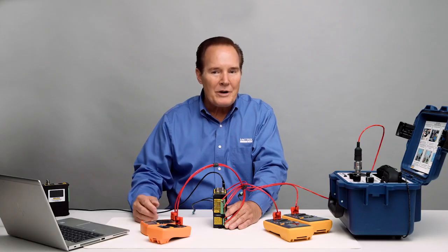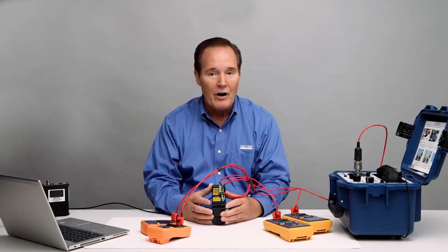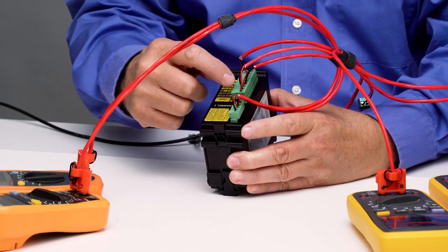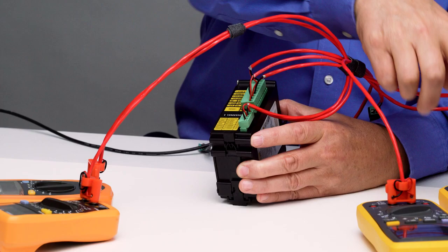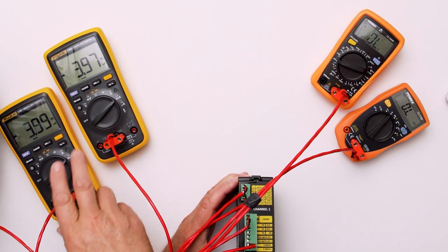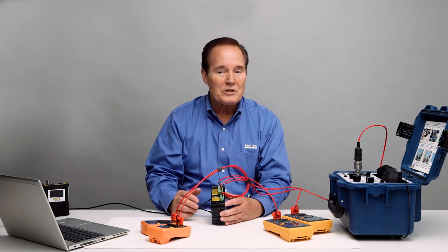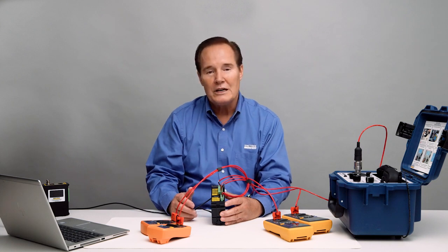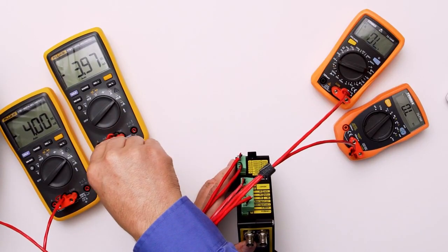All right, let me explain the rest of my setup here. I have a lot of wires coming out of here, but that's just so we have all the functionality of the system. We have the sensor coming in. We have the power coming into the device. We have the 4 to 20 coming out, and that 4 to 20 is going over to this device right here to the left. That's channel 1. Channel 2, the integrated velocity, is on the right. Now it should be right around 4 milliamps, plus or minus 5%. Well, it's well within that. It's almost right at 4, where it should be.